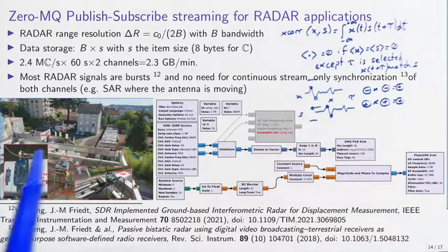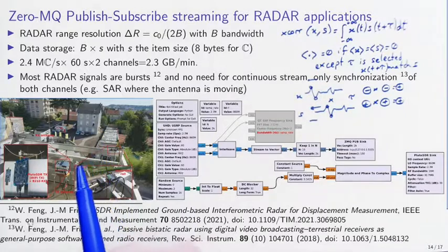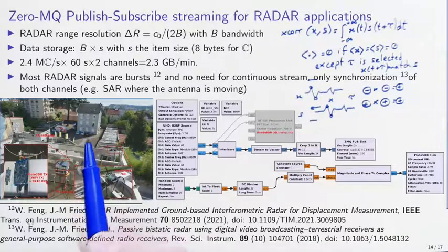So this is how radar is implemented. We send a noisy signal. This noisy signal reflects on the target and is received on the receiver side, and only when the right time delay is detected by using the correlation will we have a non-null correlation output.